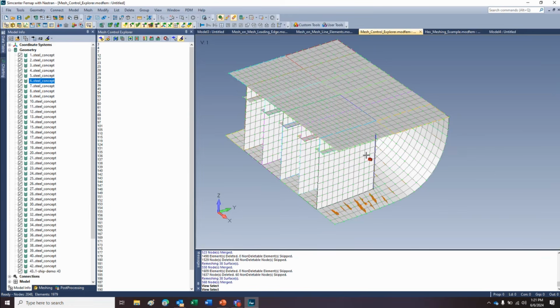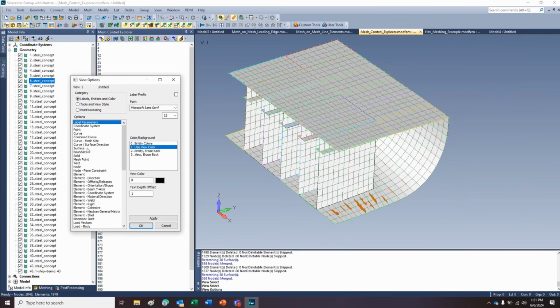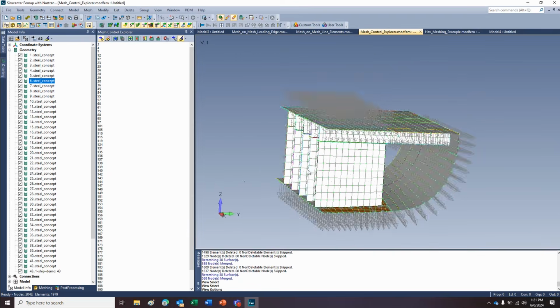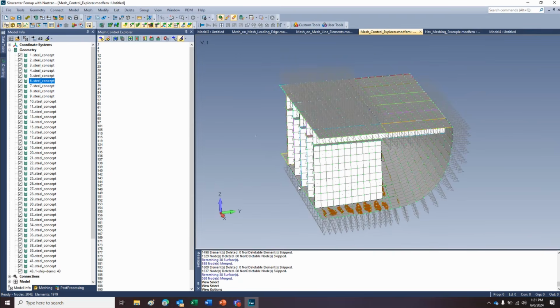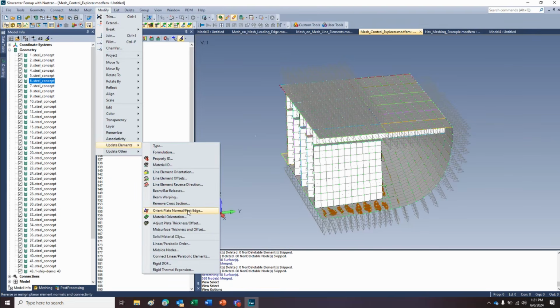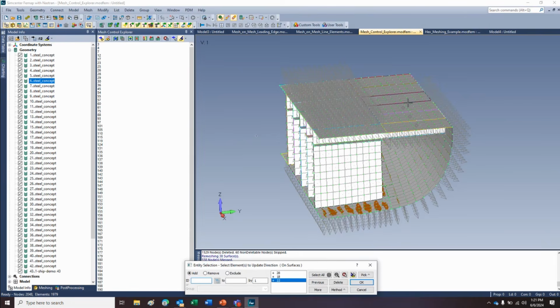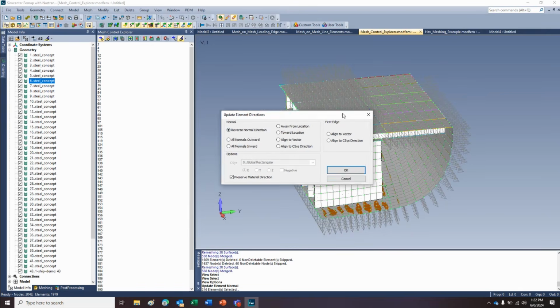But you can check that and reverse it again. Sure. Sorry. Yeah, of course. Sorry, I didn't quite understand what you meant. So yeah, at any time you can just turn on element direction, like, show me my normal vectors. Okay, so some of these are obviously going the wrong direction or a different direction. So then what we have, just so everybody sees, we have orientation normal, and then you can just do them by surface. And then again, we can just reverse the normals.